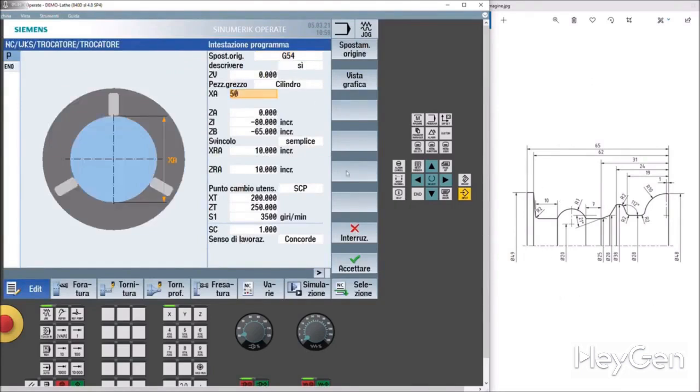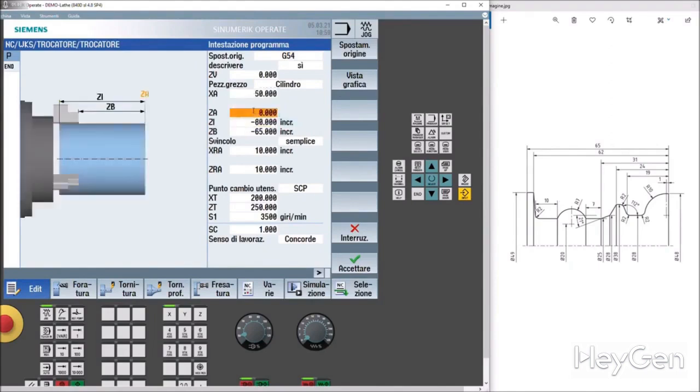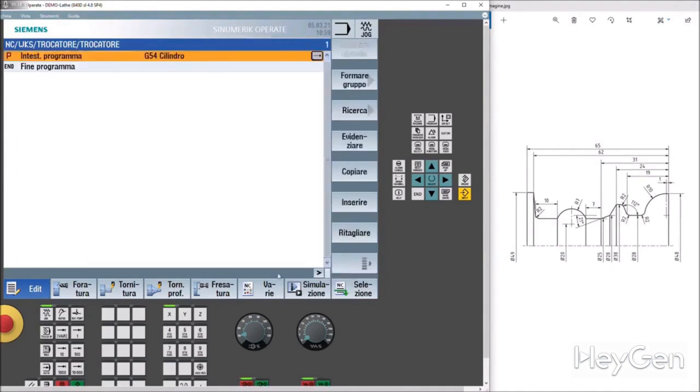The zero point essentially corresponds, because we won't worry about facing this piece. The length of the raw material is 80 mm, and its projection is 65. Simple release, since it's just an external operation, and we accept it.